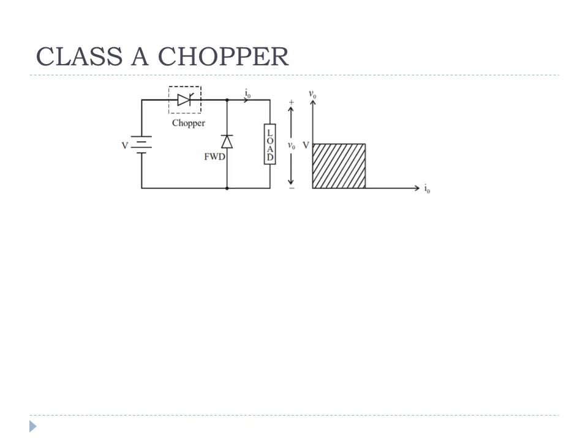We already know the circuit is a circuit of step down chopper where chopper is connected in series with the supply voltage. So when the chopper is on, the supply voltage is connected to load, and when the chopper is off, the supply voltage is disconnected from the load. So the average output voltage at the load will be less than the input voltage.